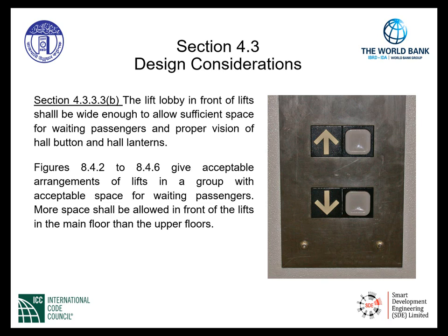Section 4.3.3.3, item B: the lift lobby in front of lifts shall be wide enough to allow sufficient space for waiting passengers and proper vision of the hall call button and the hall lanterns.